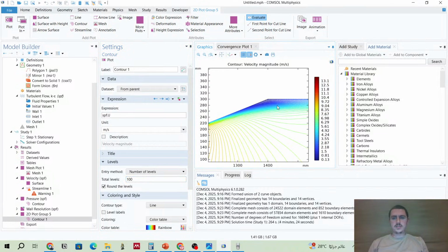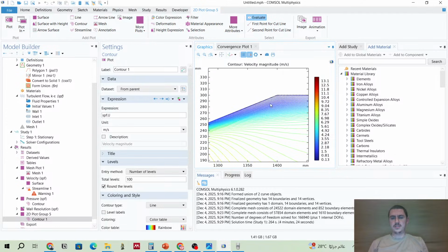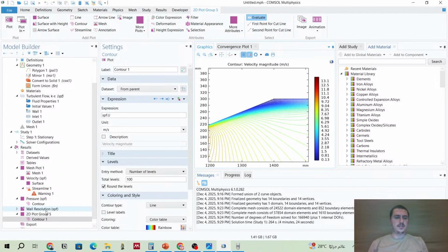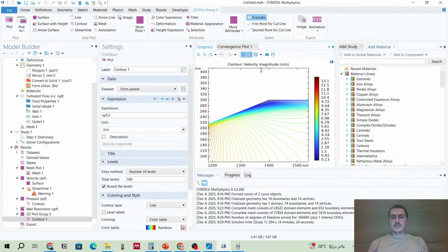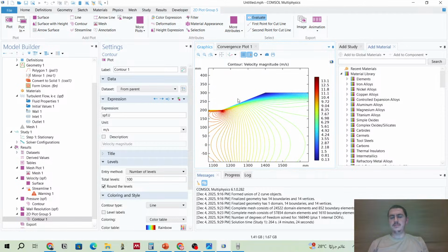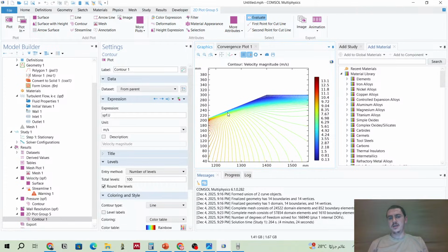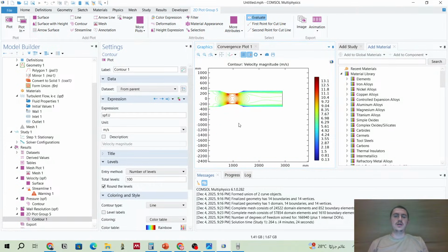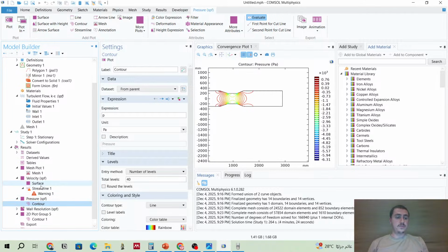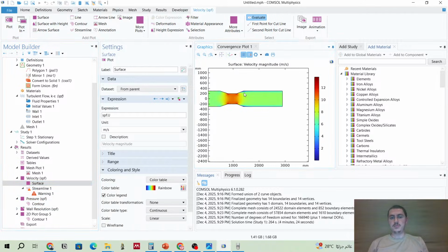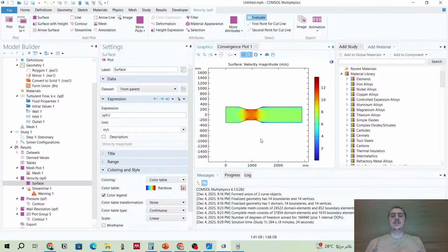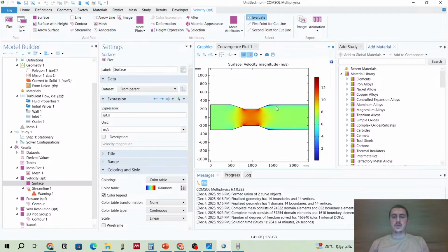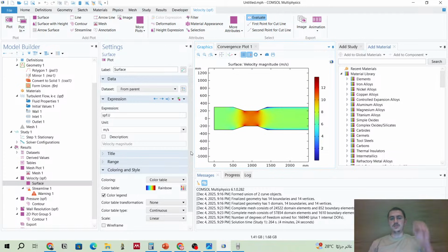Okay, so this blue stagnation point, zero points, should be the vortices side. As I mentioned, we can reduce or eliminate these vortex regimes by a smooth transition. We have a sharp edge here. We can have a smooth transition so we don't have those vortices at the blue sides. Blue zero points indicate that there is energy loss, so you should change your geometry if you want to optimize it or something else.